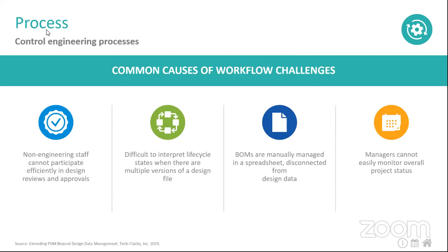What's important to the machine shop is the flat patterns. And to be able to get those flat patterns to the machine shop from your assembly, sometimes that's very difficult. Sometimes you have to manually export the DXFs individually once you open those flat pattern files. Sometimes you can use some of the Autodesk nesting software to be able to do that.